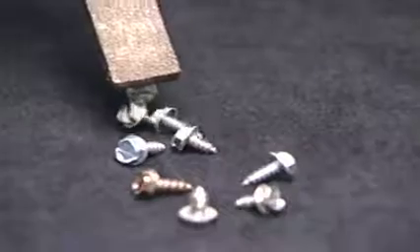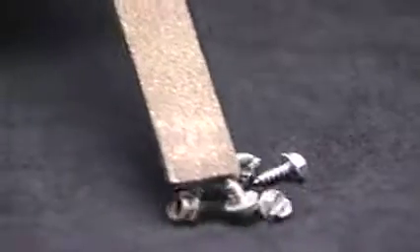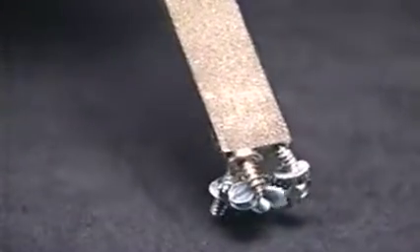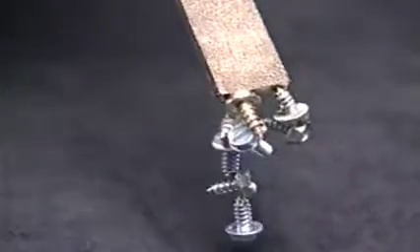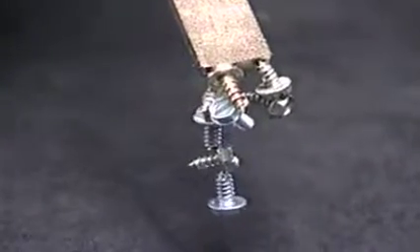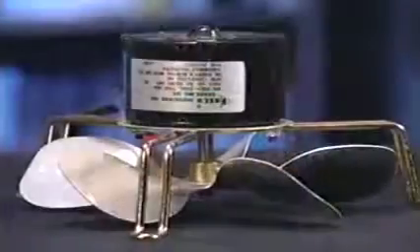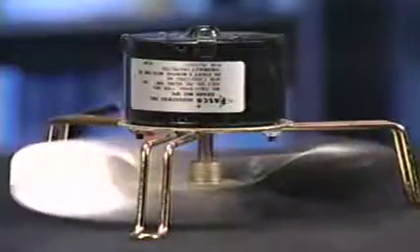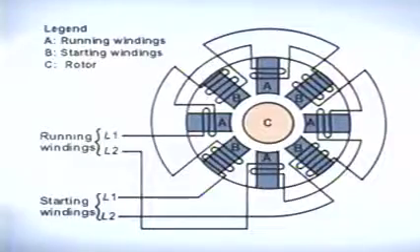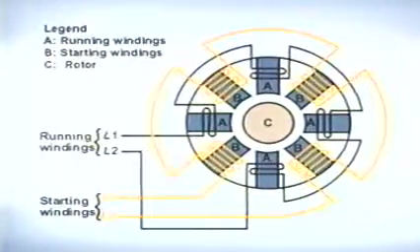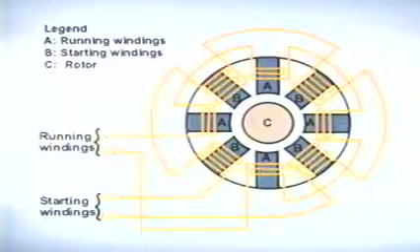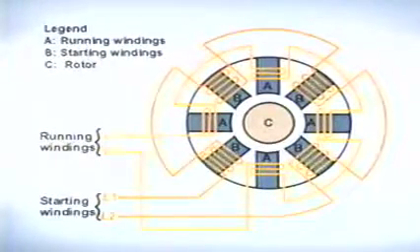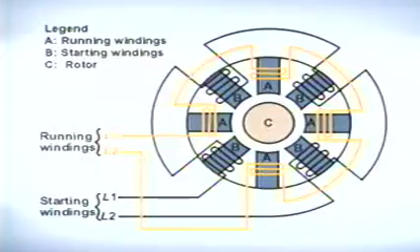Magnetism is the phenomenon exhibited by the attraction of an object to iron. The magnetic forces of repulsion and attraction cause motors to turn. Shaded pole motors rely on heavy copper bands to provide starting torque. Split-phase motors are designed with a separate start winding to produce the starting torque. The start winding is only in a circuit long enough to aid in motor starting.